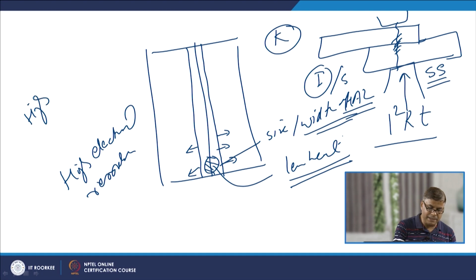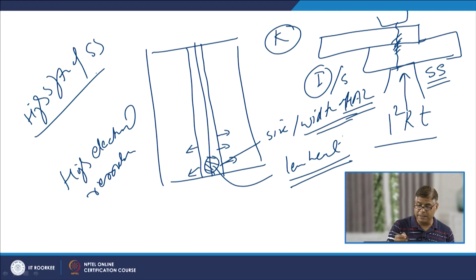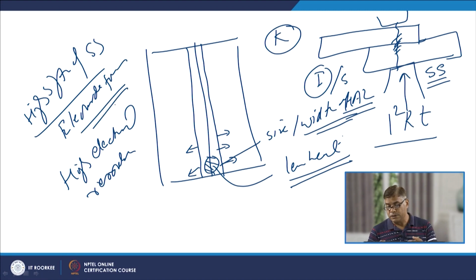Because of the higher strength of the stainless steels, especially at higher temperature, we require a greater electrode force during spot welding or seam welding, so that the required consolidation can be realized.